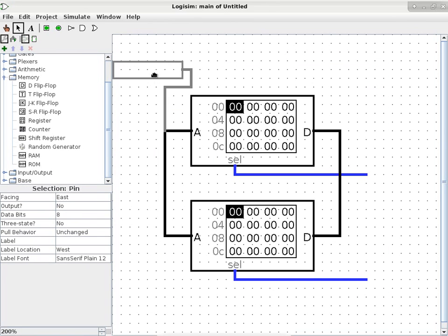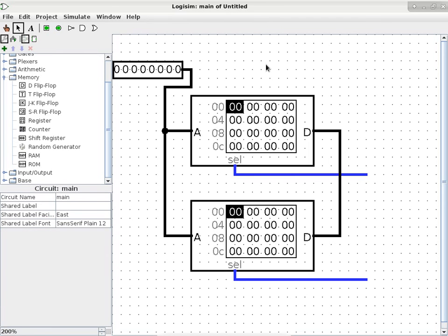And let me just move the whole thing. It looks ugly, but I guess it works. There we go. So that's how you can change the width of a quote-unquote wire to also handle multiple bits. Is that okay? Sort of? Because otherwise, it's really cumbersome if you just expose individual bits of the address bus. Then I have 8 wires to connect all over the place, which is no fun. So it's much more helpful when you combine all 8 wires and say functionally they serve one purpose, and therefore we bundle all of those individual wires into one big fat wire.